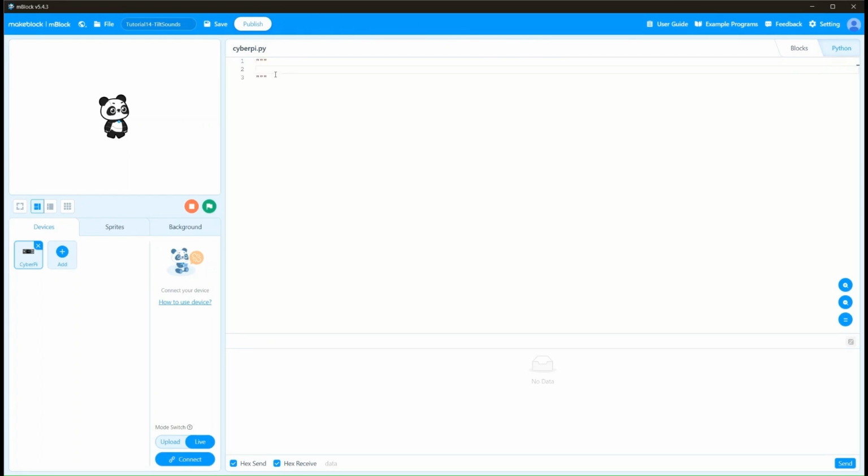As always, we will start the program when button B is pressed, and we know that we can use the button B event API from our previous tutorials. When button B is pressed, the first thing we want to do is print on the display the words detecting tilt. We then want to repeat until button A is pressed the following instructions.